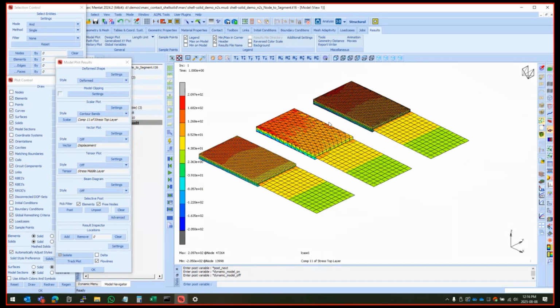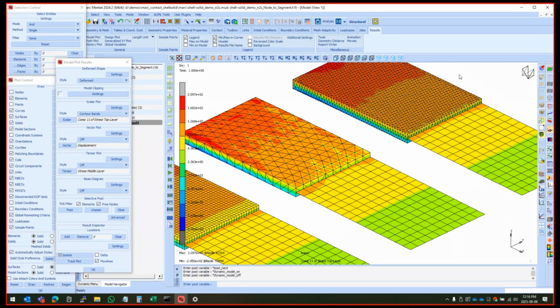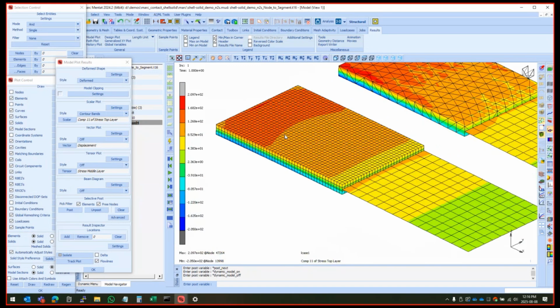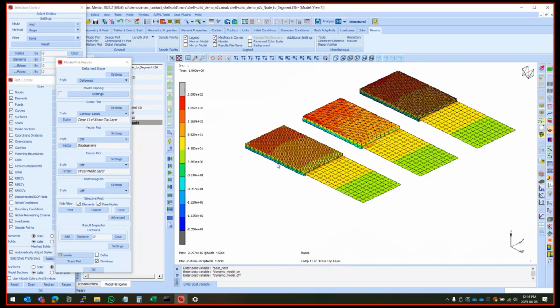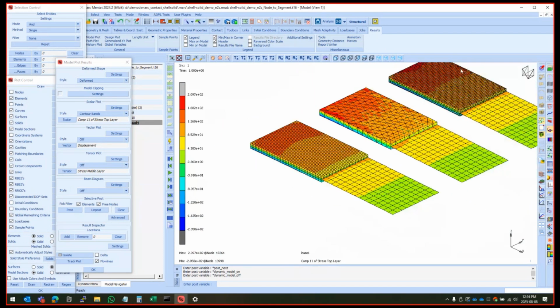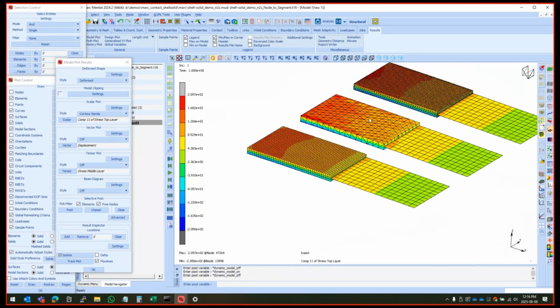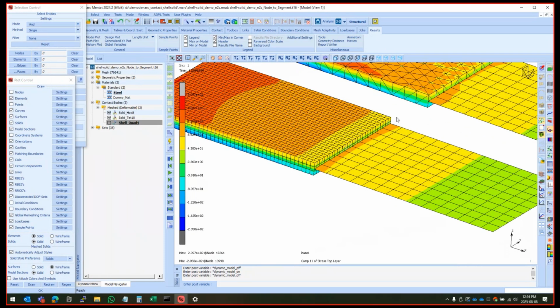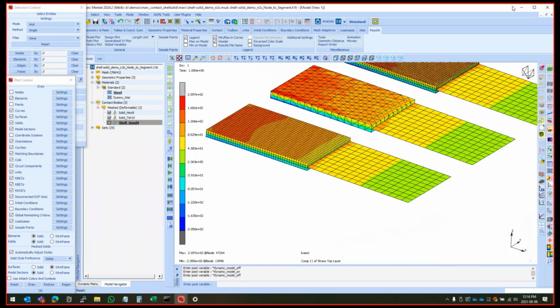But you can see as you mesh finer from a coarse state to a finer one, we start getting better answers. This is a finer but first order X8 mesh. So we already see reasonable answers for these. There we can kind of see that pattern wanting to form, definitely not perfect. Okay, so this is a much better method, but the downside is it's quite painful, as you can imagine. We have to now manually add that. We have to manually create the rigid between them. We have to manually keep track of what makes contact and what not.